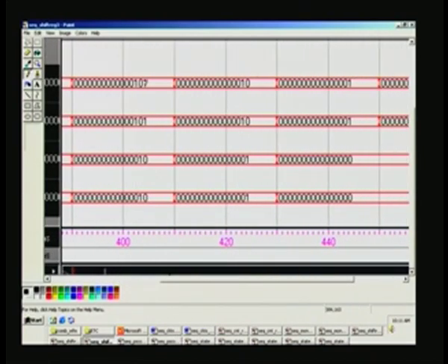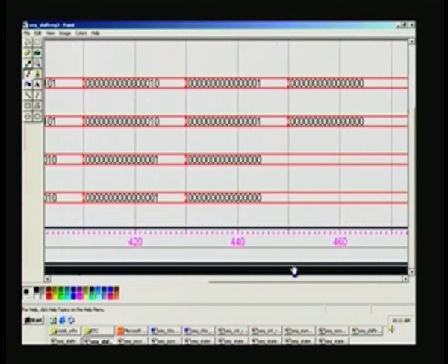You can see 101 here, all are zeros, and here all are zeros, this 1 will get dropped. So what you have is 10 here, and then this 1 will move here as shown, and finally that one also will disappear, right. That is how you see a shift register working, right.